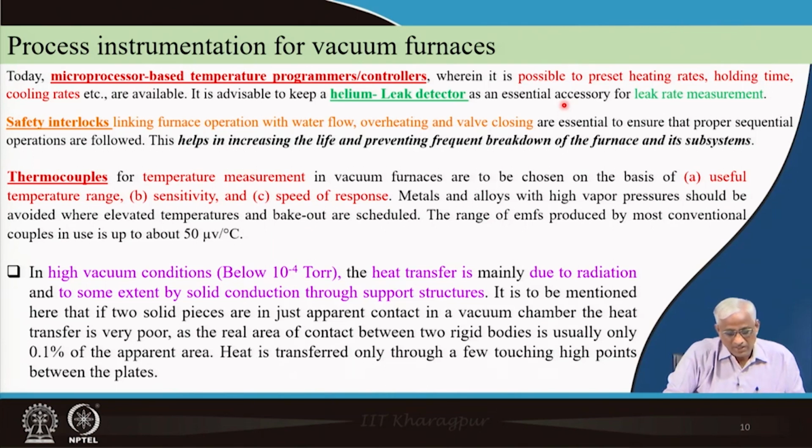You have to take all that and use the proper thermocouples depending on the range, and thermocouples should not degas, and the thermocouple end should be spot welded. You cannot braze solder, because at that temperature solder will come out, and if you twist it, the twist length should be minimum. If it is a long twist and you are touching the job and it is actually measuring, the first junction is formed at the bottom of the twist and it may be 30-40 degrees off.